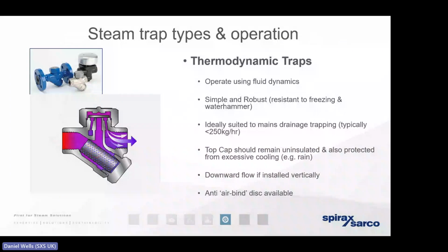The other thing to bear in mind is this is a type of trap that can't tell the difference between steam and air. So it's critically important that whenever we're selecting a thermodynamic trap, we think about the air venting upstream.